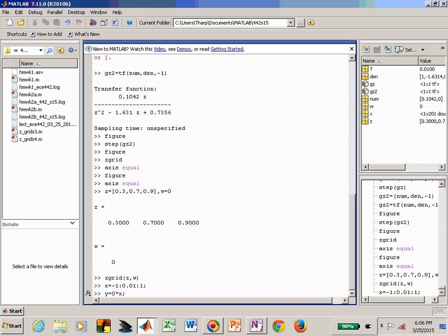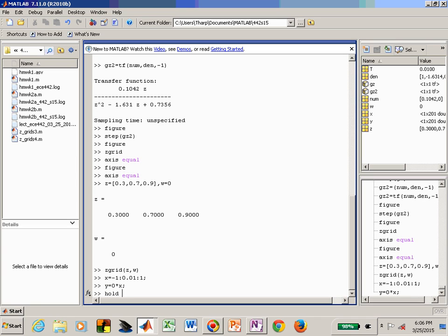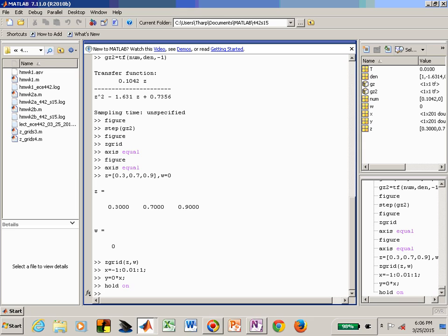I want to put that on the figure window that I just had, so I'm saying hold that figure window. Now I want to plot x versus y, and I want a black line. K is in the word black, so that's where the K comes from. Because if you just said B, maybe you'd think it's blue or banana or something, but K is black. That's pretty obvious, right?